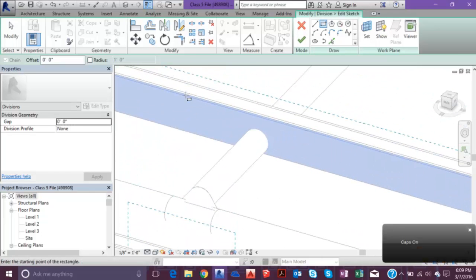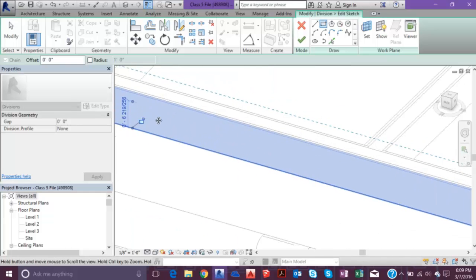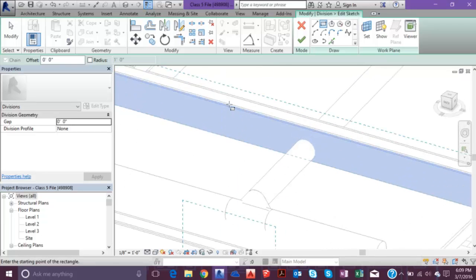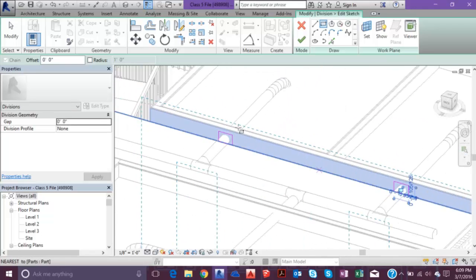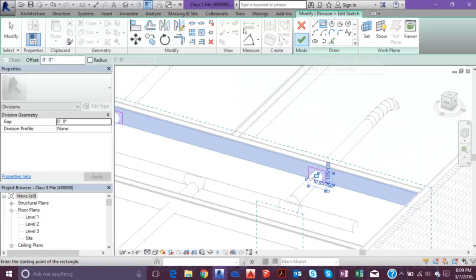And we're going to go right up to this wall, and we'll make a rectangular opening right here. And because this ductwork goes through the wall here, we'll make another rectangular opening on this wall. And instead of dividing the part 2 times, we're dividing it once, the reason being, if we do it a second time, like in the last video, it'll just exclude this part of the gypsum wallboard, and that's a fiasco. We're much better off doing it this way.